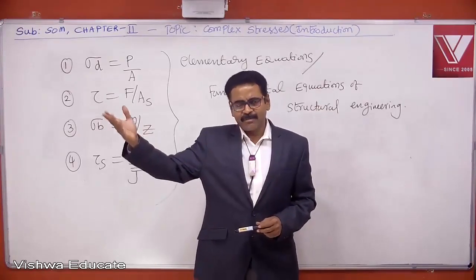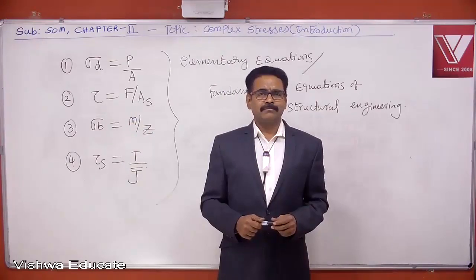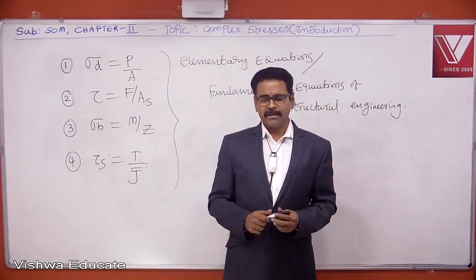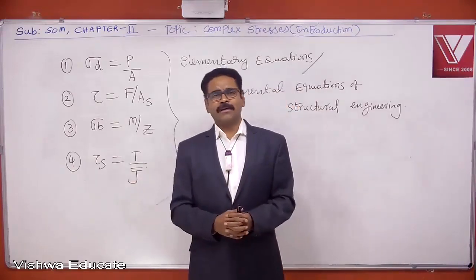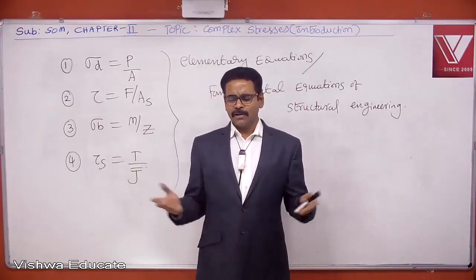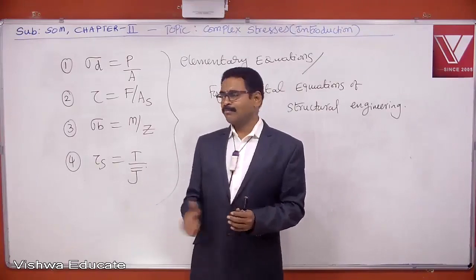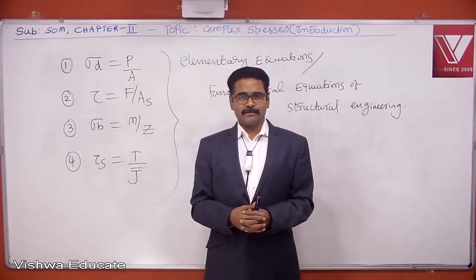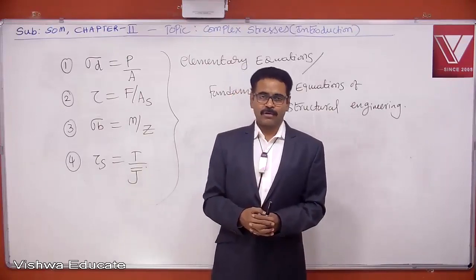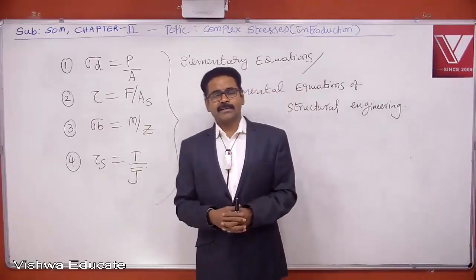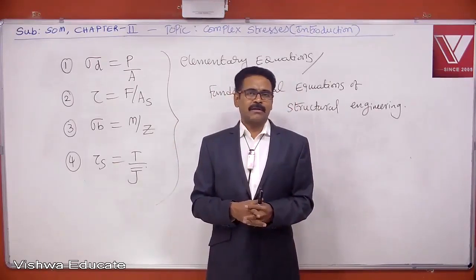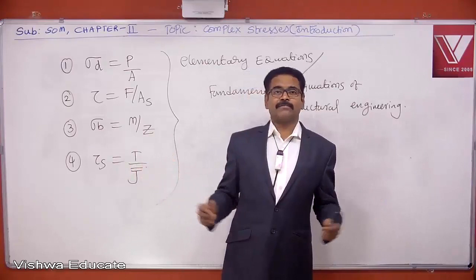Ductile structures fail about the shear plane. Brittle structures fail about the principal plane, the major principal plane. All these things we should know how to find. Otherwise, you cannot design any structure. Simply following the formula gives no guarantee of safety. If you design your structures on the basis of major principal stress and maximum shear, your designs will be more safe.